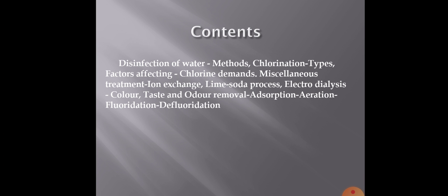So we know that we have discussed so many methods so far, various methods of purification of water, starting from the screening process, plain sedimentation, sedimentation with coagulation, filtration, etc. So we must understand that either singly or in a combination, whatever processes we have discussed so far is not sufficient, or we cannot rely upon these processes, that is the sedimentation, coagulation, filtration, etc. It cannot be relied upon to remove the bacteria that is present in water, especially the pathogenic bacteria.